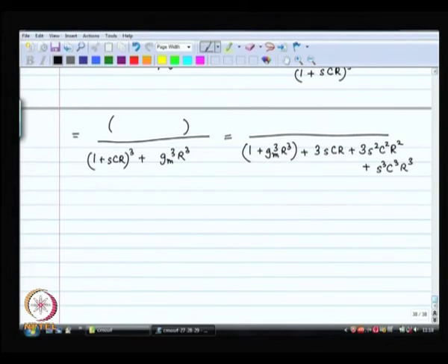If I had just two inverters in series with feedback, then first of all I would not be getting the negative sign, I would be getting a positive sign here. So, that is a problem. Okay. So, it is not going to create negative feedback, it will work as a latch. It is going to create some positive feedback at DC, it will work as a latch.